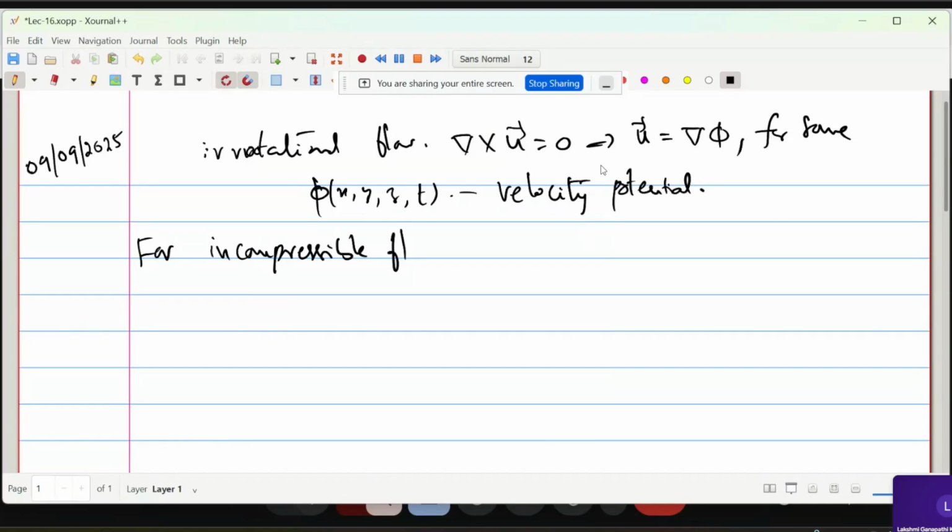The ∂u/∂t term is there, but without it, only for steady flows can you do this, right? If you include that ∂u/∂t term as it is in the rotational form that we have done now, that Bernoulli function we brought in, dB, grad B plus ∂u/∂t, that momentum equation, you can't do anything. So it is the same as the original momentum equation and whatever the other main equations that you have.